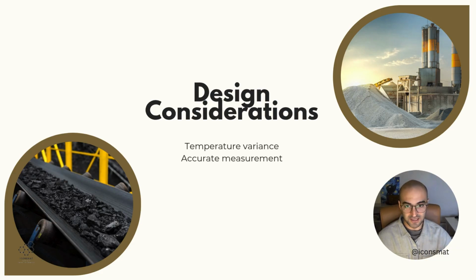If you remember from the previous episode, load cells are basically a really long, tangled, conductive material that deforms as the load is imposed on it. And the deformation, based on Ohm's law, would change the resistance of that conductive material, and that change in resistance can be converted into voltage changes, and that voltage change can be converted into a kilonewton value or a kilogram value. So the basis of load cells relies on Ohm's law.